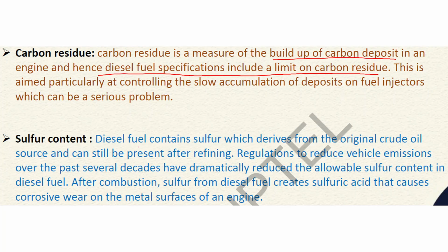Then the sulfur content of the diesel fuel should also be low. Otherwise, after the combustion, the emission gases will consist of harmful gases such as sulfur dioxide, and an obnoxious sulfur compound smell will be present. Therefore, to reduce that, sulfur content should also be limited.